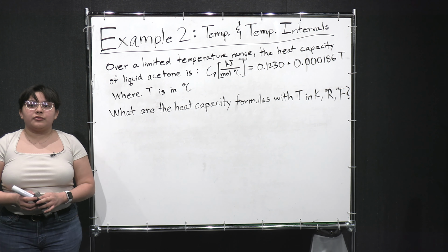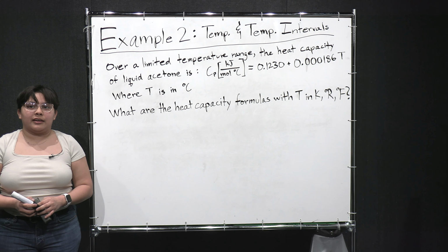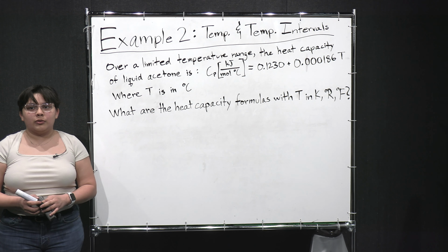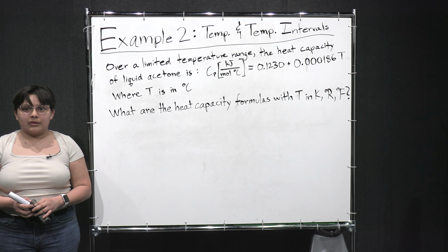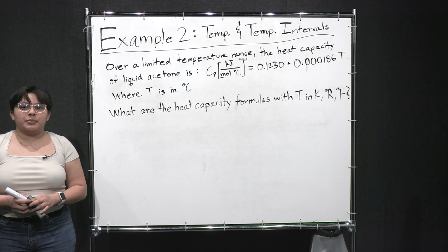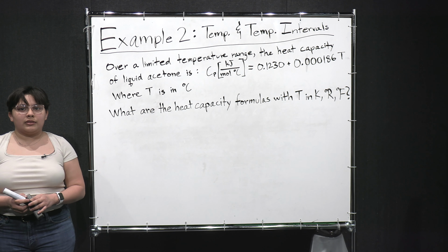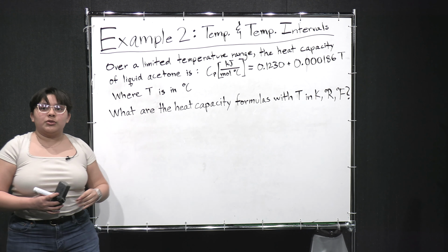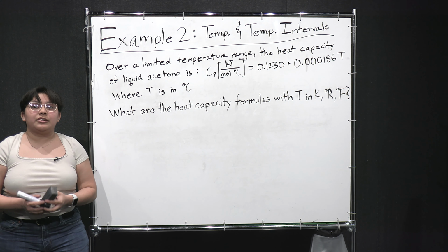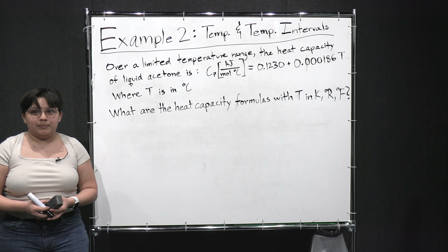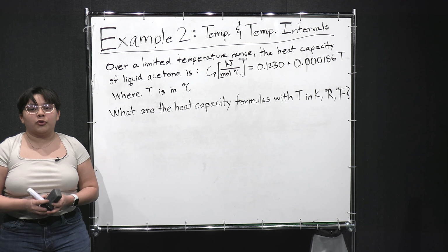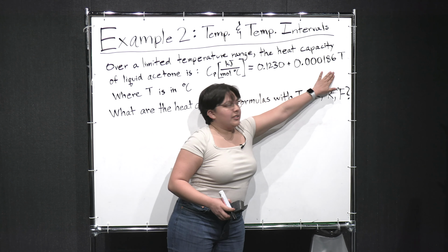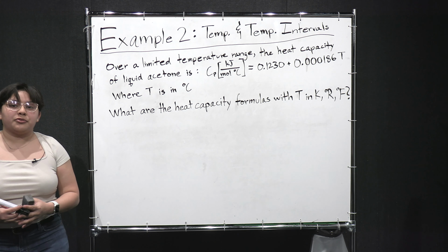The full procedure for converting an equation with dimensions is discussed at length in the Most Annoying Equation Conversion video. If this example seems confusing, go and watch that video and then come back. We start by looking for temperatures and temperature intervals because they need to be converted differently. The left side of the equation, the heat capacity, C sub P, is used only with a change in temperature or a temperature interval, in other words, per degree C. So we must convert it with the temperature interval formula. The right side uses the actual temperature, T, so we must convert it with a temperature formula.